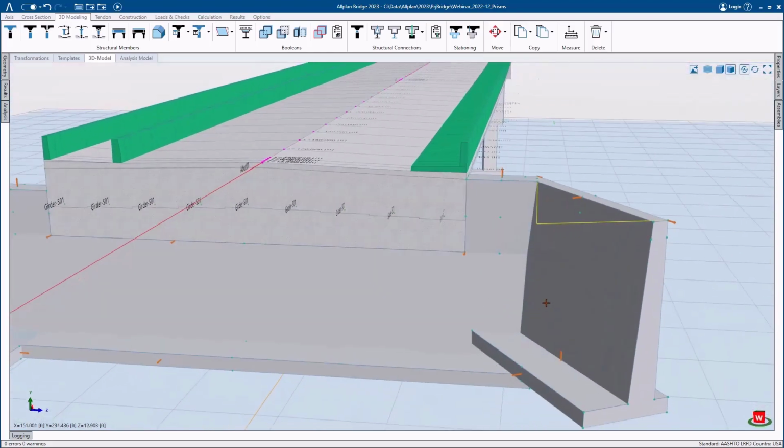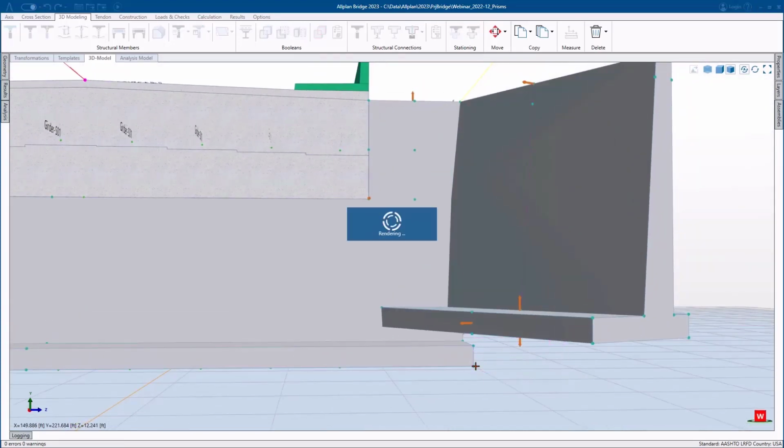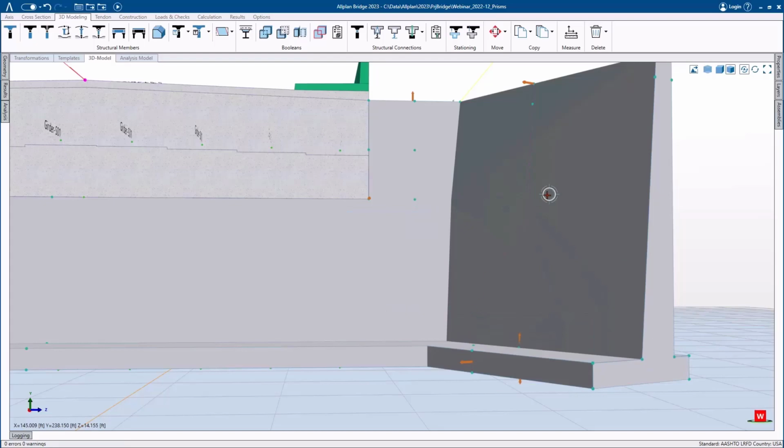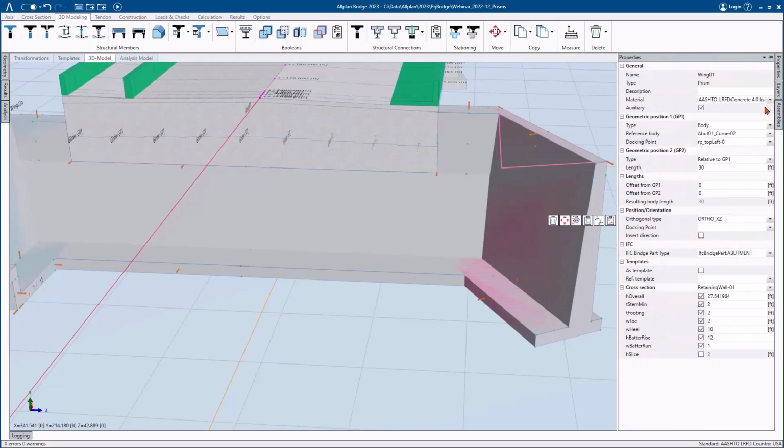Of course, now the height of my retaining wall itself needs to be adjusted, but again, it's a simple process of selecting the relevant slider and moving it back into position. I can express some more finite control over the whole object. For instance, I can select just a portion of the overall abutment, and then I can view the properties, and let's say I need to adjust the width of the retaining wall's heel.